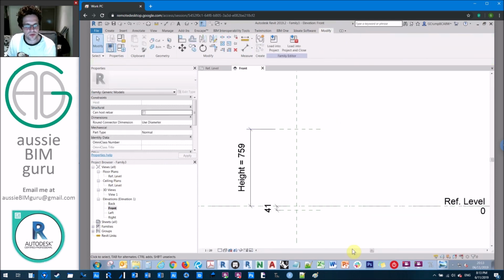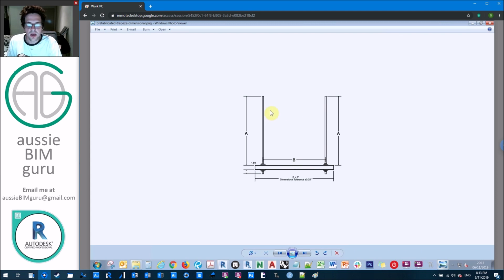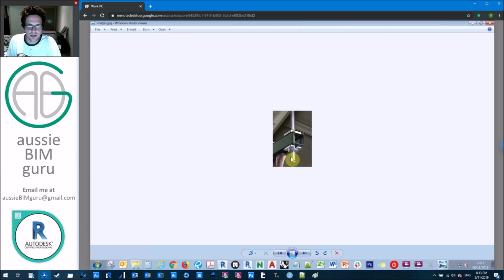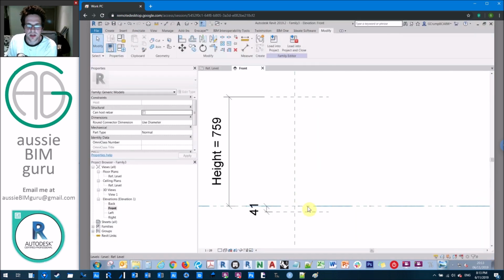So now what we want to do is draw some components for our Unistrut dropper. Typically these elements will have a plate above and below the Unistrut. They're all different, of course, they're not always the same, but I'm going to do this scenario. And then a bolted thread that runs through the Unistrut up to the top of the slab, where it's typically either bolted, chem set, or fixed to the slab somehow, or it's clipped onto a beam. But essentially what I will focus on in this case is just this fixing first. And it's all hosted around this reference plane, really.